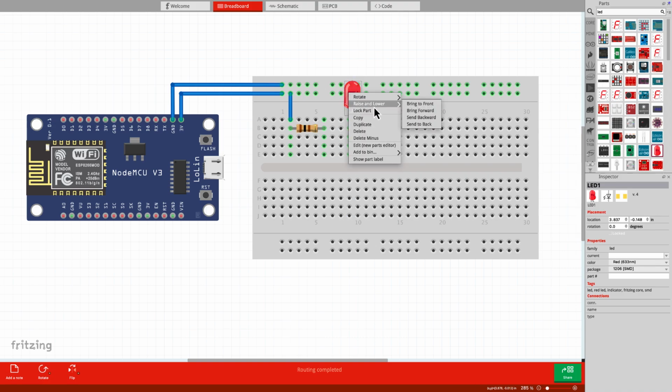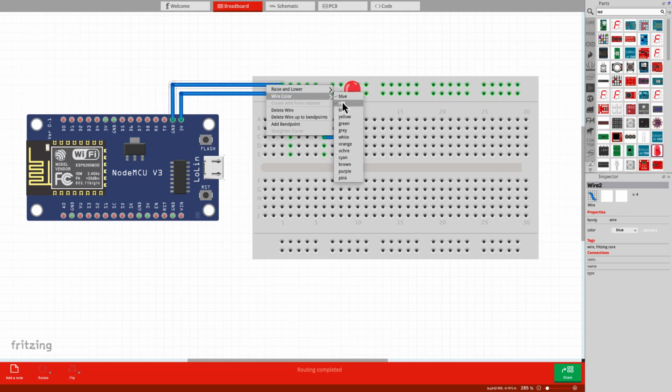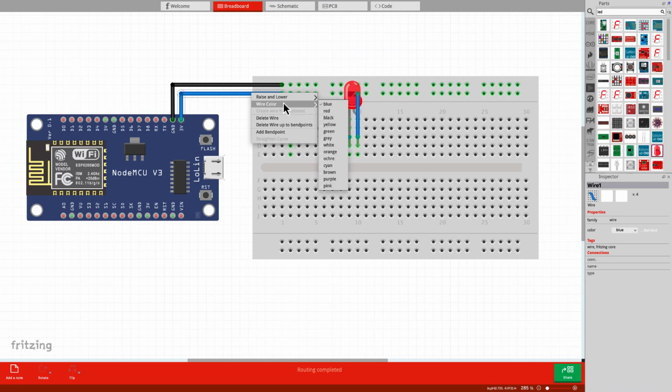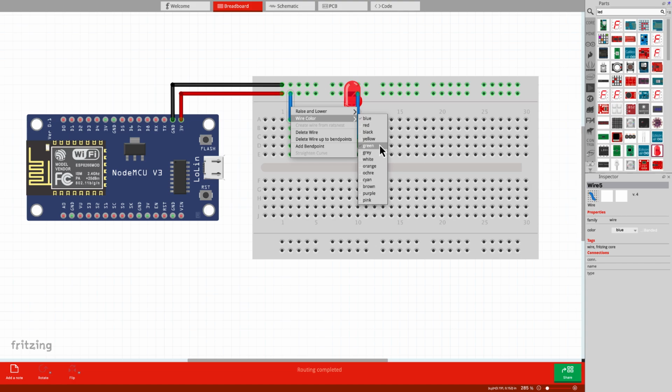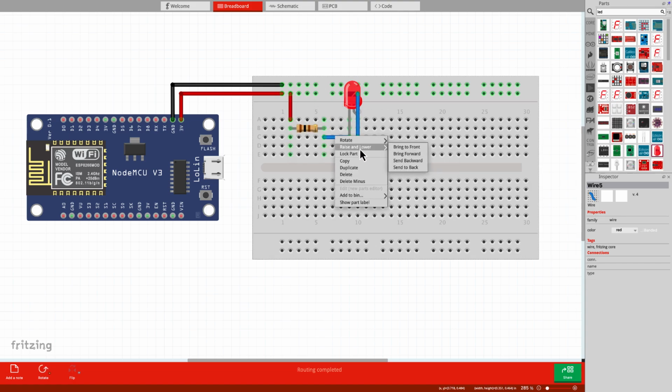One thing to note over here, one leg of the LED, or one connector of an LED, will be shorter than the other one. This basically indicates an anode or cathode, that is a positive terminal and a negative terminal. In most cases, if you plug the negative terminal to the wrong side of the power, you will end up burning the LED. That's why we are using a resistor to stop excessive current flowing to the LED, thus preventing a short circuit.